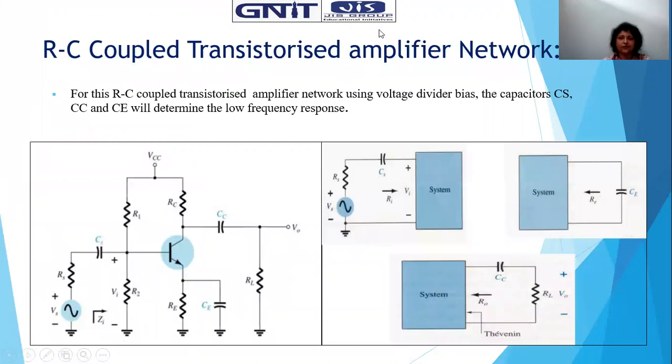So if VCC is grounded, what we get here is R1 from base to ground, then R2 from base to ground. Then we have RS, which comes through CS from VS, and that we have to incorporate. As well as the RE model of the transistor, where the base-emitter junction is reflected as beta R, and IB is the current.